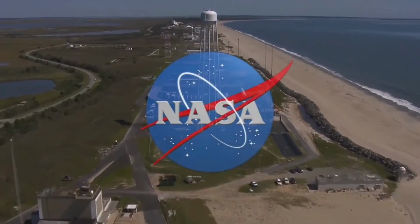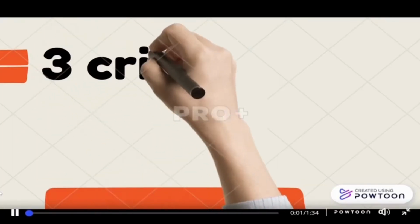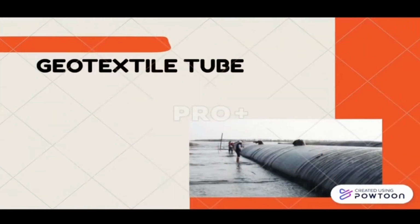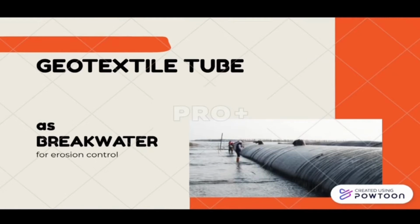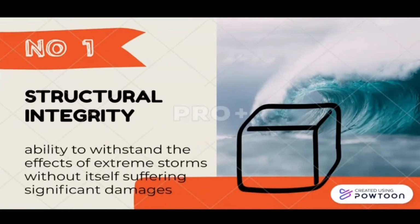In order to overcome this problem, geotextile tube as a geosynthetic material will be used. The Drainage and Irrigation Department and USACE manual draws out that a functional design of geotextile tube as a breakwater for erosion control must fulfill 3 main criteria. Firstly, structural integrity, whereby the geotextile tube must have the ability to withstand the effect of extreme storms without itself suffering significant damage. Hence, wind and wave records must be observed in order to determine the dimensions of the geotextile tube.